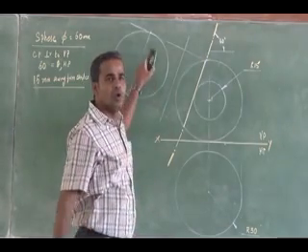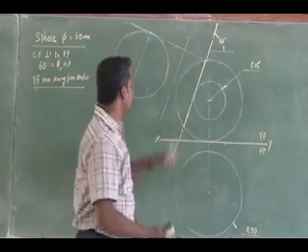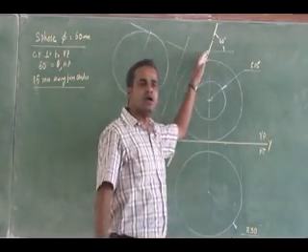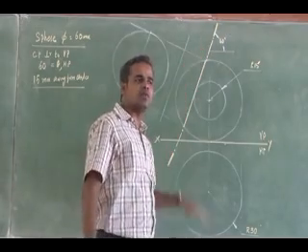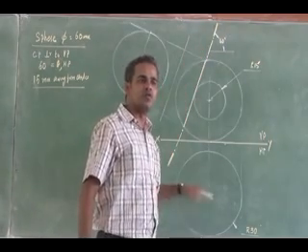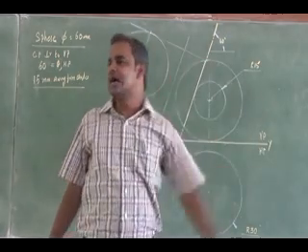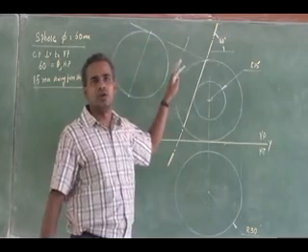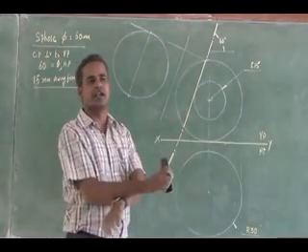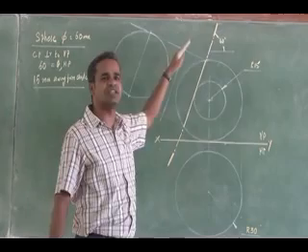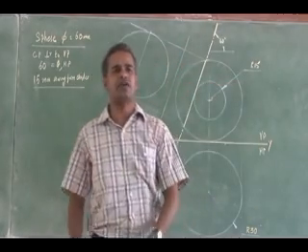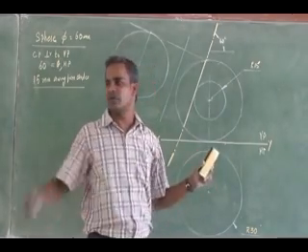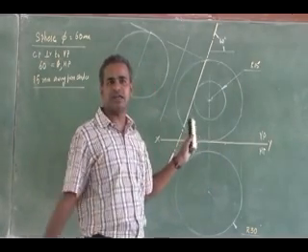Then, as far as the sphere is concerned, we cannot proceed similar to your previous problems. We will be marking the cutting points and going for the sectional view. From the sectional view, we will go for the true shape of section. As for a sphere, the true shape of section is defined. In whatever orientation I cut a sphere, the true shape of the cut will definitely be a circle.